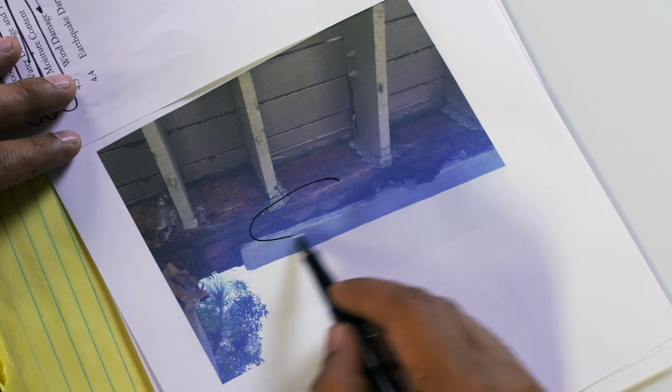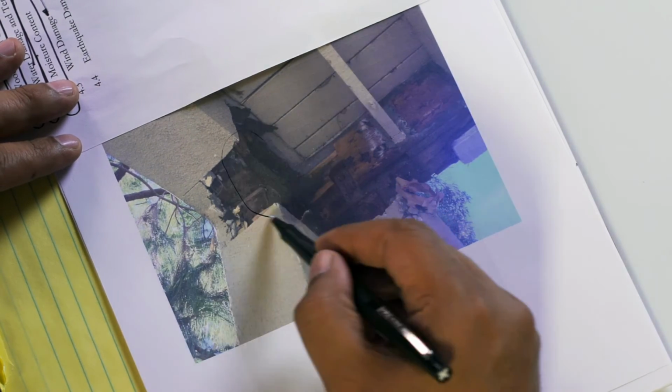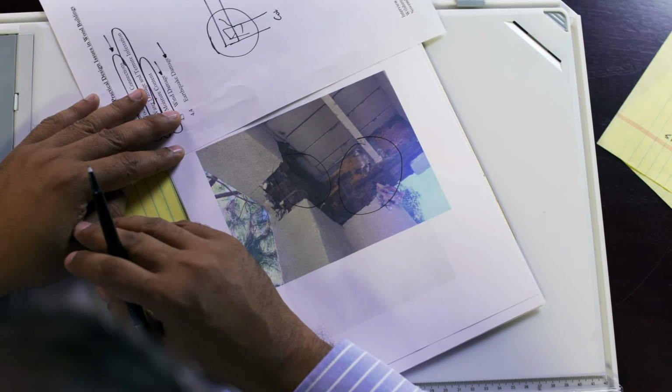And again, on it goes, one after the other. And it gets worse as you go to the connections. The interesting thing about these pictures is that if you look at the stucco, everything looks nice and clean. Everything looks pristine. But the minute you take the stucco off, you see that the entire structure is about ready to fall down. So what did I have to do in this case? I had to flag off the building. I had to tell them not to go on the balconies until we could go and replace this. And again, if we hadn't opened it up to go look at it, we wouldn't have a clue.